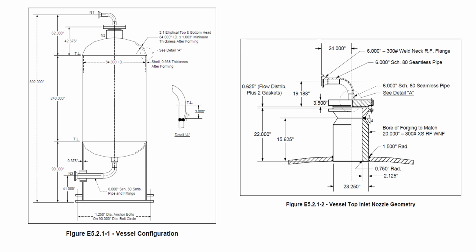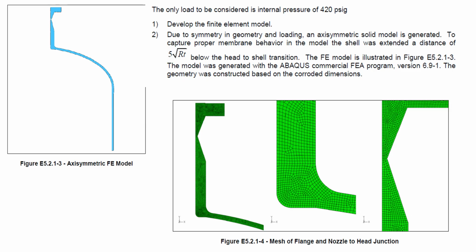Vertical vessel supported on the skirt, and the dimensions are provided here to construct the 3D model geometry. Here the mesh model is shown, and the axisymmetric model is made using Abaqus. But since we are using Nastran, we will slightly modify this model in order to suit the similar boundary condition as well as the mesh size.